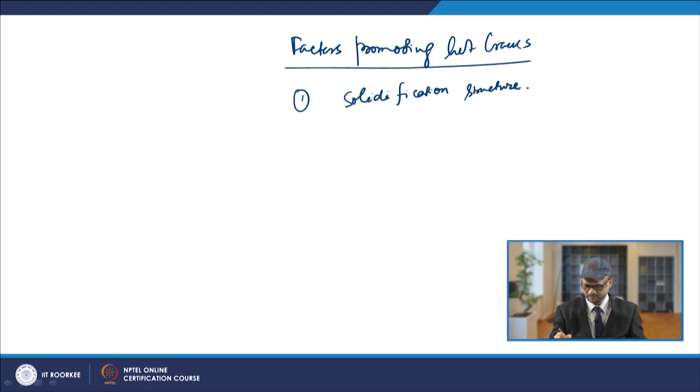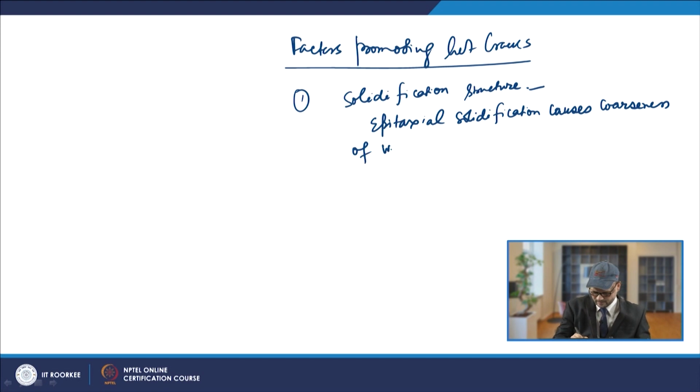So epitaxial solidification causes coarseness of the weld deposit, which is also inherited from the grain growth zone of the HAZ.